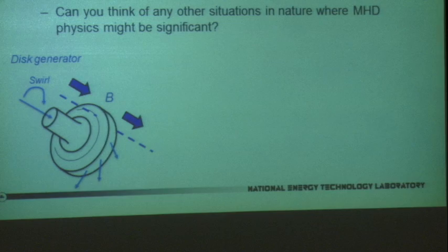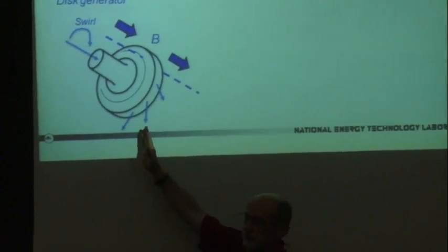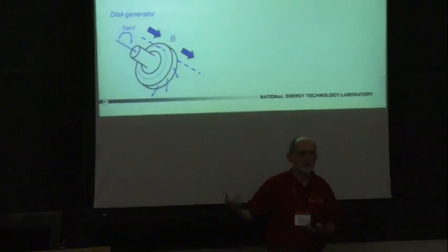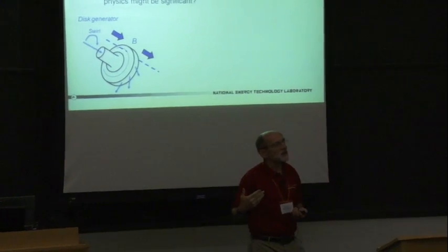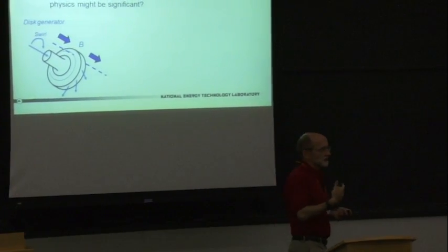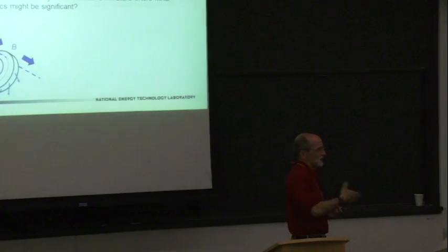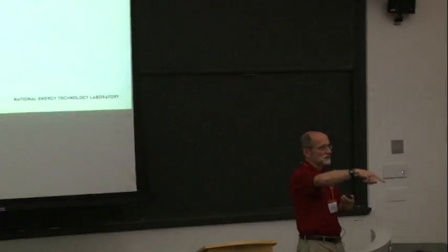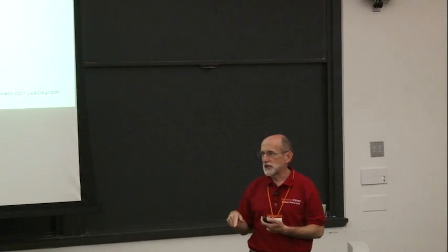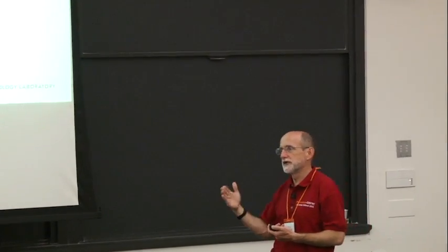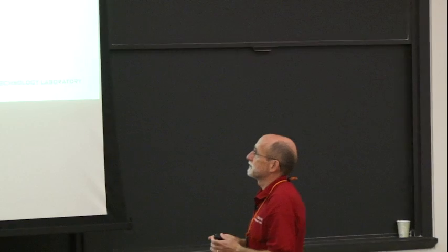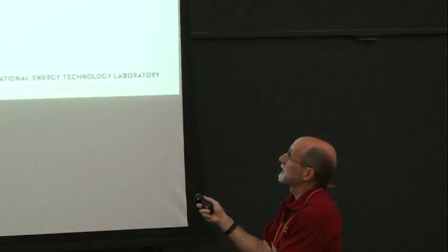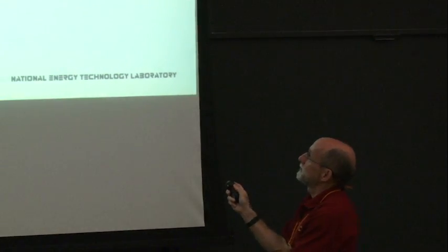But I'll mention there are people who would say you could take advantage of that swirl, who would realize the flow is going to get swirled by its interaction with the electric and the magnetic fields. It's not going to come out straight because it's got a force on it, so it's going to start swirling. So you actually have a chance to take advantage of that if you configure the flow field correctly relative to what's going on with the magnetic and electric field. And this is just a fun one. Go out to the internet.